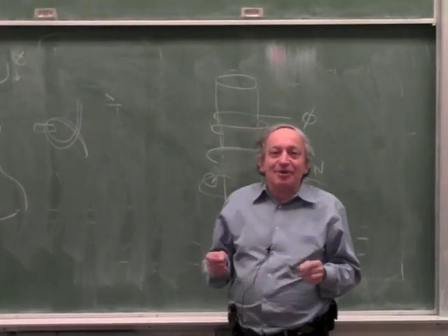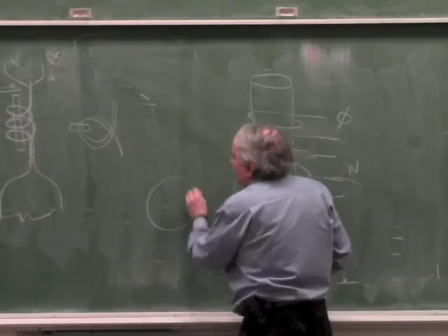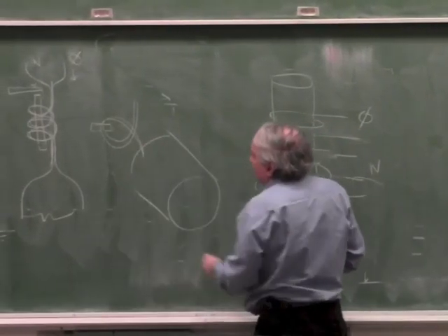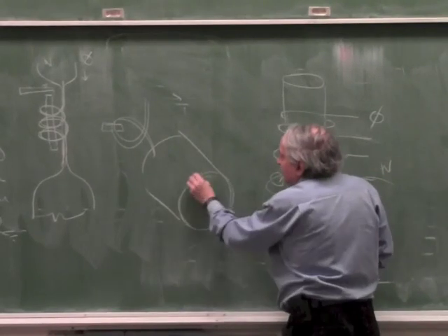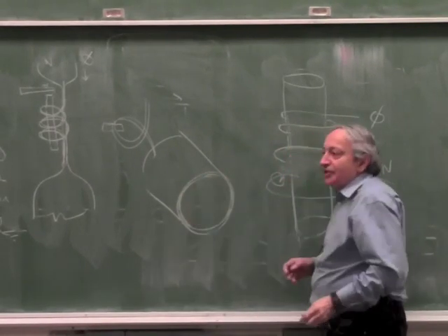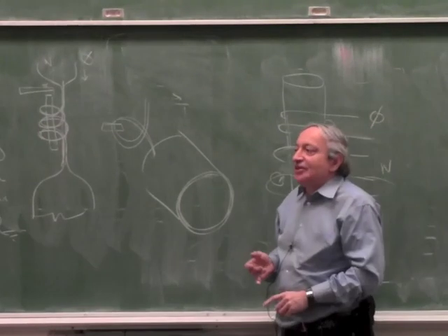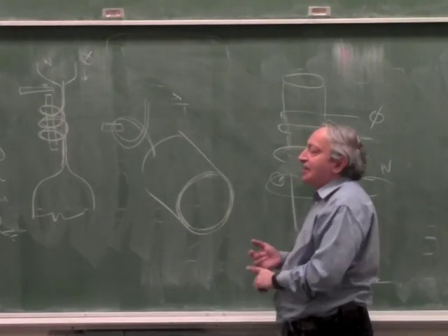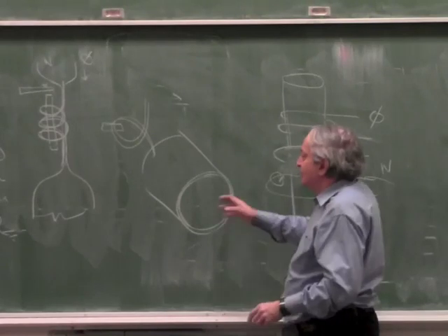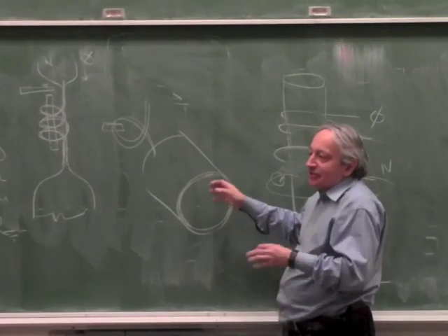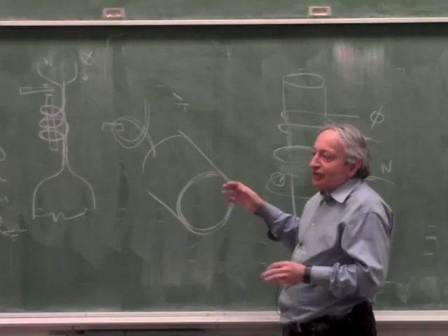Okay. So remember, at high frequencies, when you have a conductor, the current doesn't flow through the whole conductor. It only flows on the skin, and the depth of the skin is a function of the frequency, of the dielectric, and of the magnetic constant. Since metal is not dielectric, it's not magnetic, it's basically just a function of frequency.